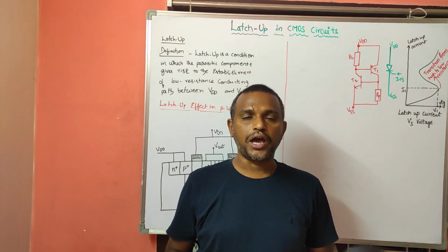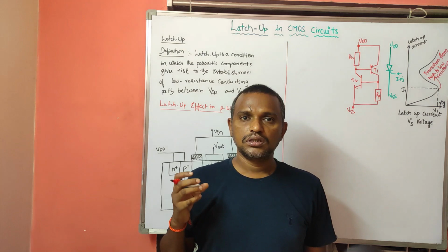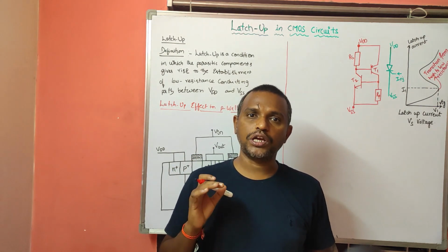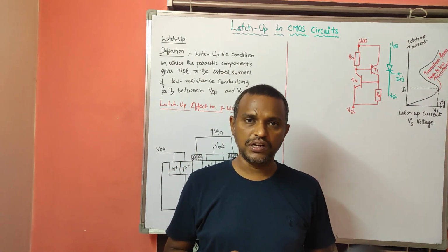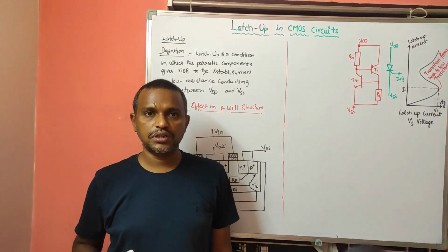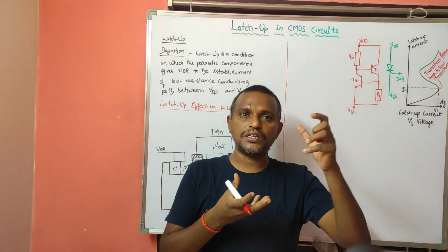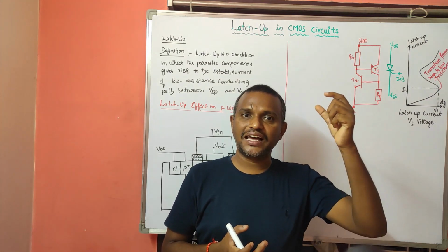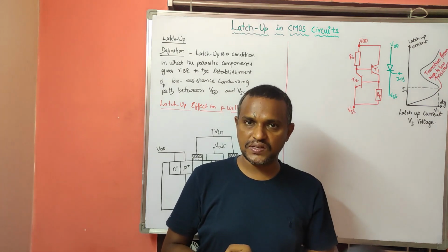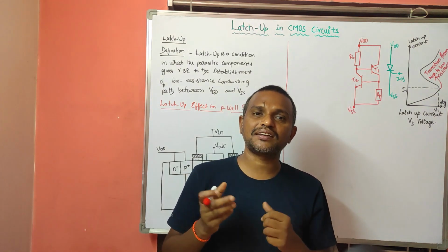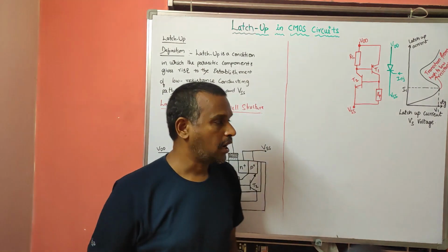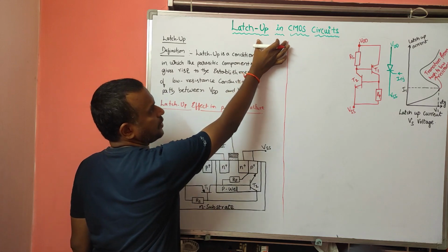Hello everyone. Today I am going to explain the latch-up condition in CMOS circuits and how we can avoid these latch-up conditions. We will see now. Okay, so what is latch-up? Latch-up is nothing but the establishment of a direct connection, or a low resistance path, between the VDD and VSS rails due to the parasitic elements. That is called latch-up.